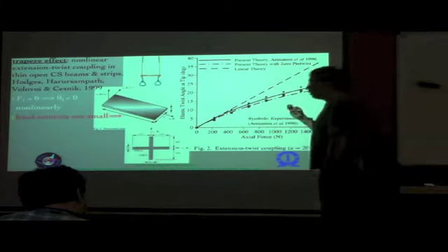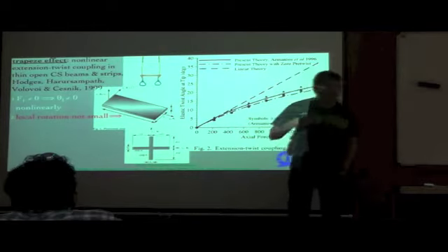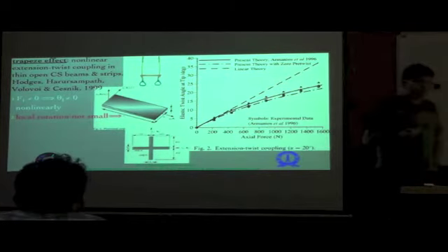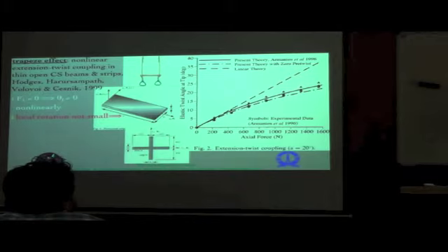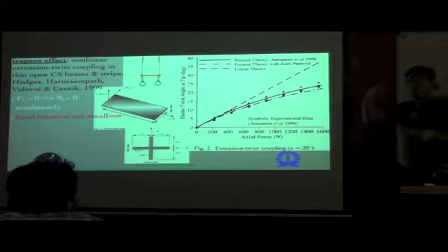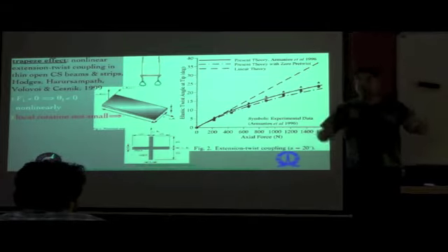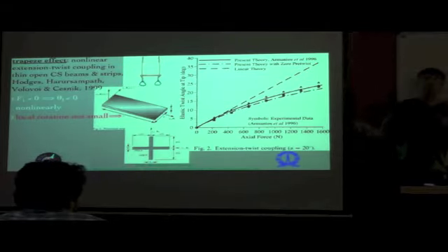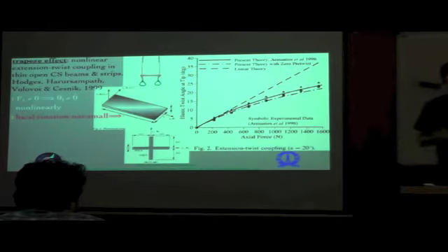Now what happens here is an out of plane warping, whereas the previous example was an in-plane warping, where you saw that the circular cross-section became ovalized, in other words the shape of the cross-section changed. In other words, the W2 and W3 warping components were primarily non-zero.